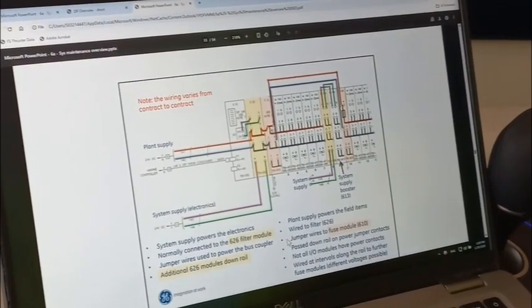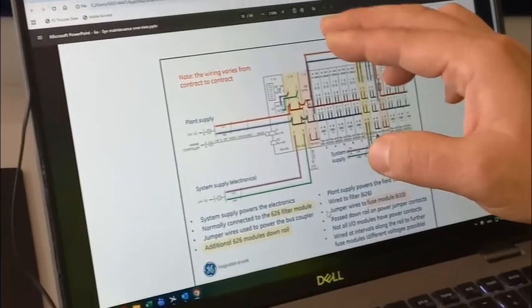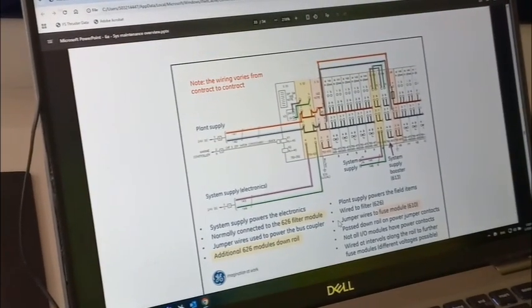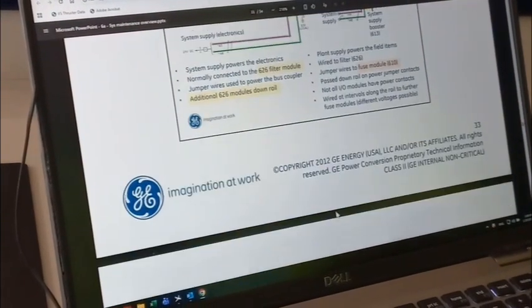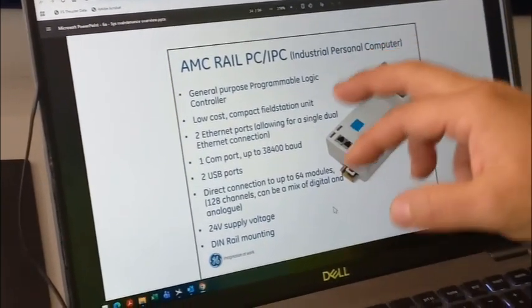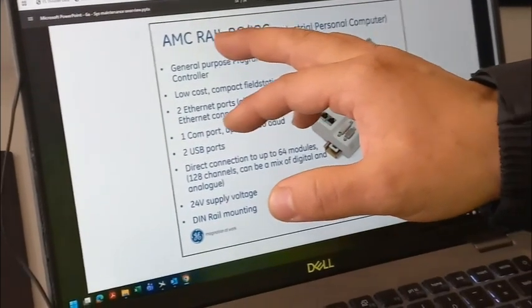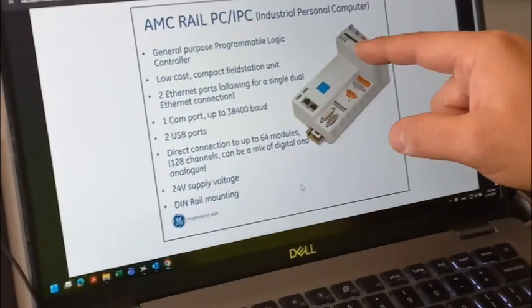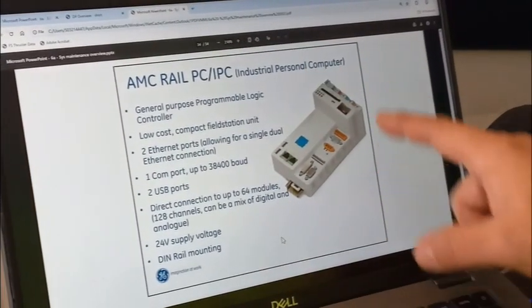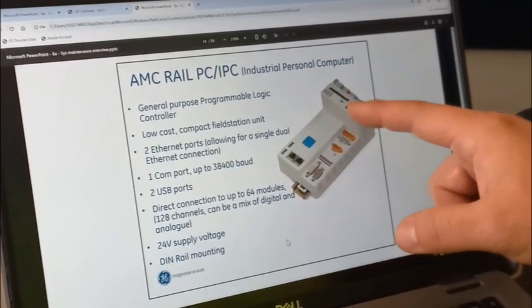You can check if the fuse is blown. You need to refer to the internal drawings, which will show you where the power comes from. Normally, it's the fuse on top. You remember there are 3-4 fuses there. Actually, it's not that difficult. That's an old A series or C series DP system. We used to use the Wago rail IPC controller. It will have a CF card there to have the software running as well. But now this is obsolete. It's not in production. You don't have this one.